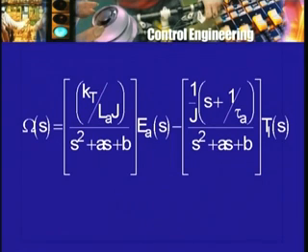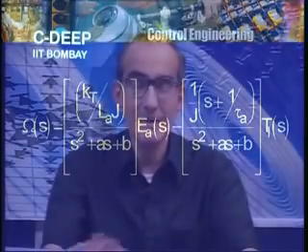So we have two poles which are common to both the transmittances, but only the load torque transmittance has a zero. And so as we did earlier, one can draw the pole-zero diagram. In fact, I am going to do that very soon. But before we go to that, I now have a system which can be represented as follows.